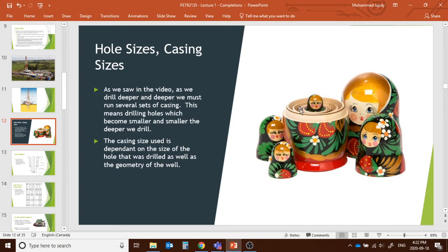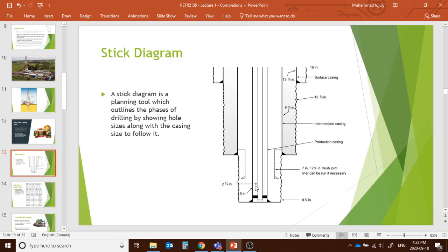So when you drill and put the conductor casing, after that we do the cement lining inside, and then we put the casings and cement lining inside, and so on until the production casing goes in there. Okay, so this is the 2D version of the stick diagram, how the casing actually looks. It's a more elaborated version. Okay, so that is how you put the casing.